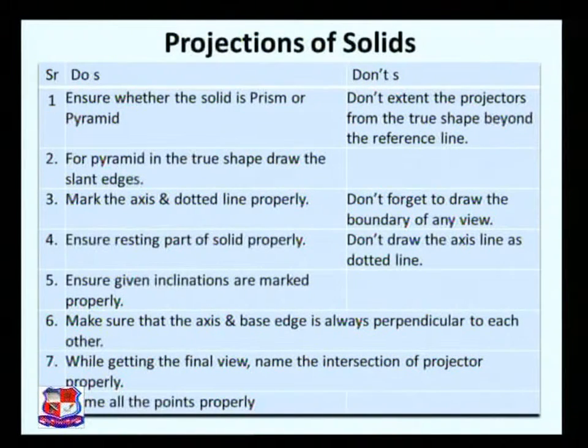Fourth, ensure the resting part of the solid properly. Properly ensure that the solid is resting on its base or its corner. Don't draw the axis line as a dotted line. The axis line should be drawn as a full line. It should not be drawn as a dotted line.